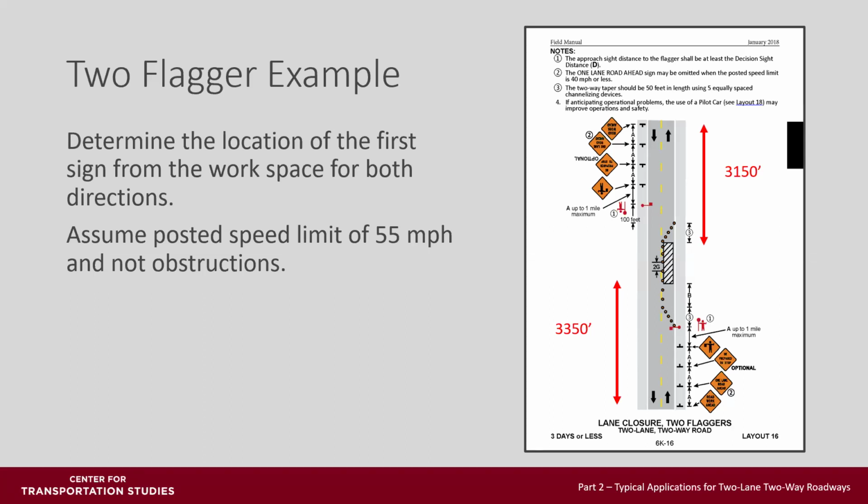As always, you install the temporary traffic control devices in the order in which drivers see them and remove them in the reverse order. Details and variations are included in the field manual and were covered in part 1 of this webinar series.